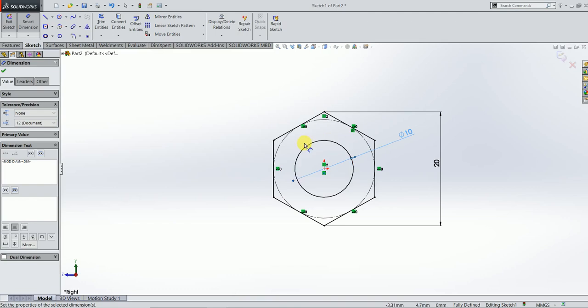So you need to remember, okay, M10 thread is given for the nut, meaning the inner diameter of the nut is 10 mm. Then the distance between the corners of the hexagon should be what? 20 mm. That is 2 times 10. So this proportion you should know.